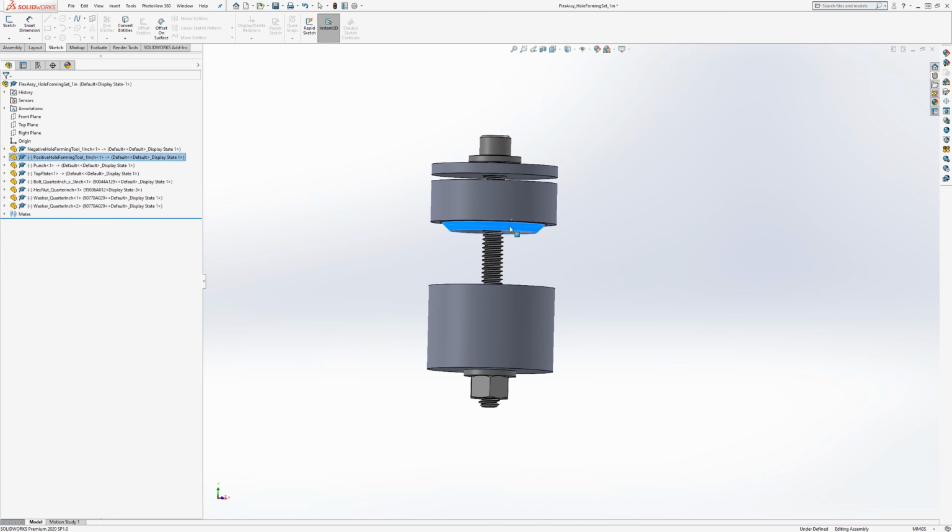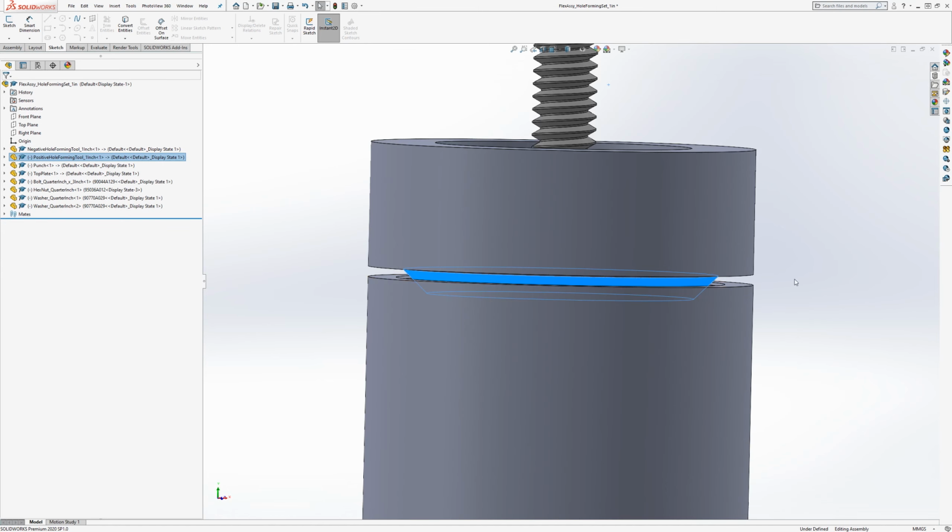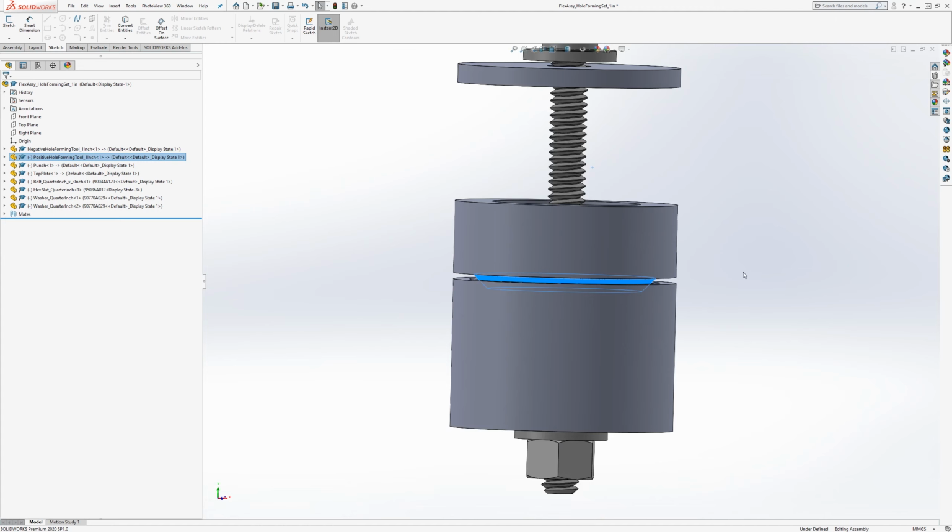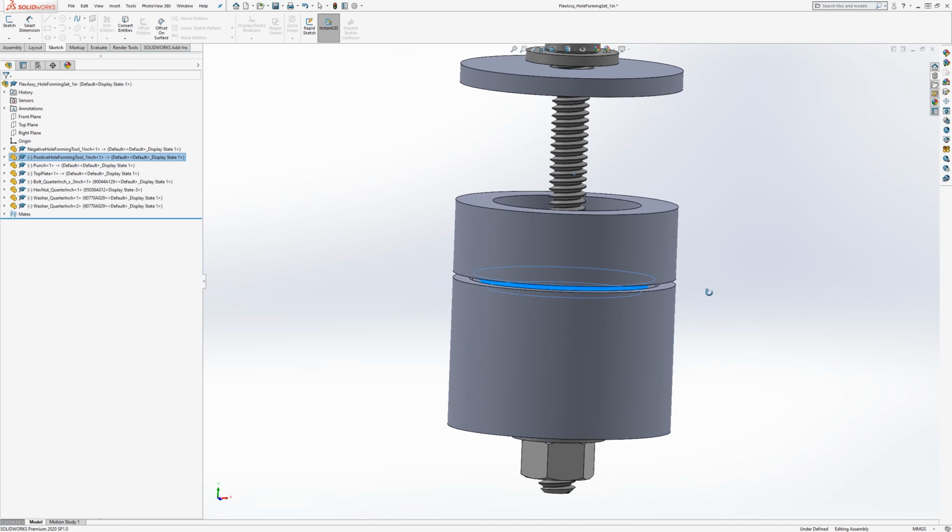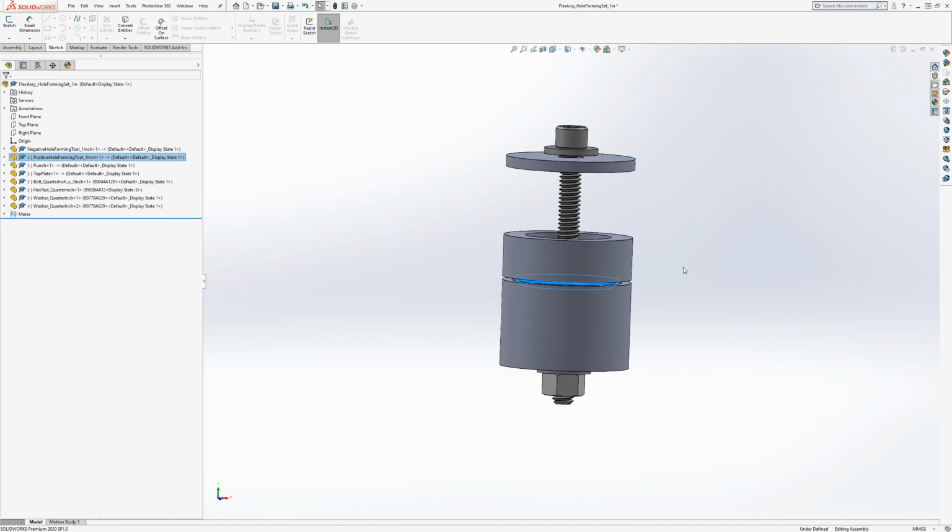And when you tighten this down on it, it will form a flange around that hole in the sheet, which stiffens the hole. You could find that often in aircraft, for instance, in sheet metal webs of beams. If you want to create some holes that lighten the beam and stiffen those holes, you stiffen the whole web with those flanges. And then of course you can pass systems like wires and hoses through those holes.